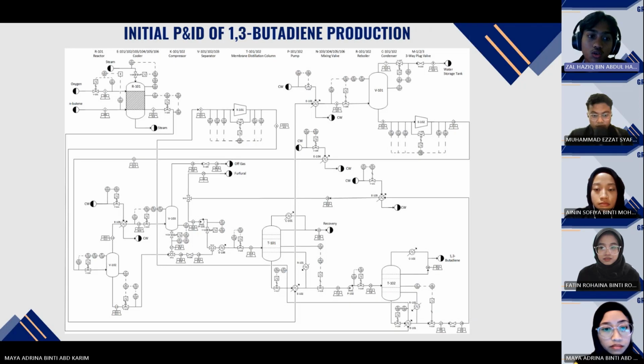Then, the substance goes through 3 separators where the byproduct furfural is removed and then is distilled by 2 distillation columns. The oxidative dehydrogenation of N-butene is an exothermic reaction where heat is removed by steam for steam generation. The reaction yields and selectivity range from 70 to 90%, making it unnecessary to recover and recycle the feedstock.